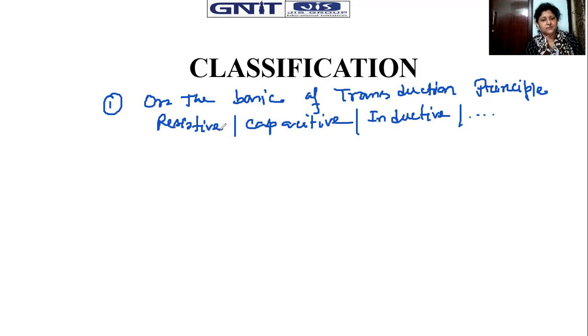That means the resistance value will change with respect to a certain amount of physical energy. Like the capacitive property of the transducer will change with respect to a certain amount of physical energy. Okay, so we will observe basically del C in that case, we will observe basically del R in that case, we will observe basically del L, suppose, in the case of inductor, and del M in the case of mutual inductor. So like that, it will contribute.